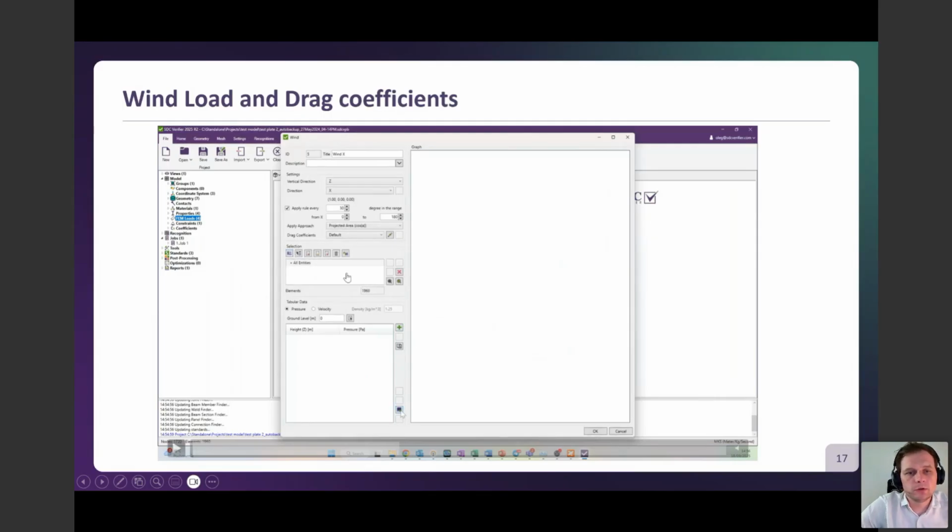But what you're able to do is to define the elements subjected to wind in this rule-based selector, where you can select by element type, property type, or, what's more important, by coordinate. So you just measure the coordinate of your first edge or face and define all of those.